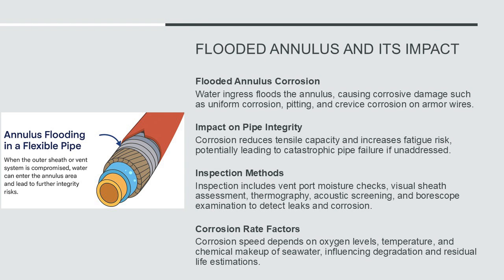Inspection strategies for flooded annulus involve vent port checks for moisture and chemistry, visual assessments for sheath damage, and advanced techniques like thermography to detect cooling signatures indicative of leaks. Acoustic or ultrasonic screening and borescope inspections at end fittings provide further evidence of wetting and corrosion.